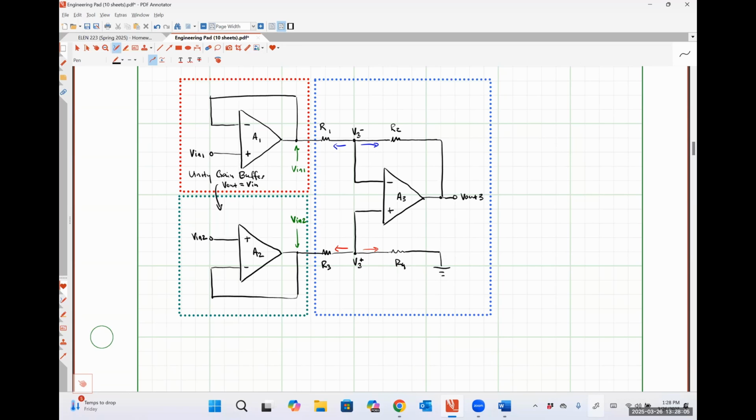And then if we just look at what's in the blue block, where R1 is equal to R3 and R2 is equal to R4, it is literally the differencing amplifier that we derived the relationship for in our last class meeting. So we could, if we had broken this guy up into individual stages, literally not worried with any of that algebra and come out with a relationship. V out is going to be equal to R2 over R1 times Vn2 minus Vn1 if we were paying enough attention. So now I have concluded my lecture on cascade amplifiers.